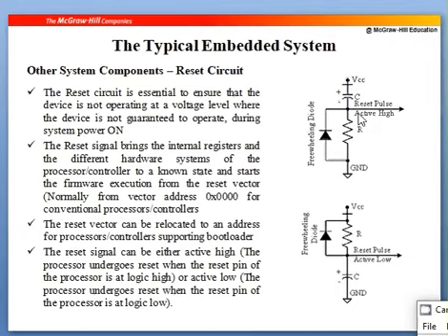Initially this will be active low, and it is pulled to active high when the VCC supply falls below a certain voltage. Similarly over here, initially the pin will be in the high position. Then when the supply goes bad, this will be triggered to the low position. So it is used for functioning your reset. This will be used if the pin accepts a high signal. This will be used if the pin accepts a low signal. If the reset pin takes active low, then you have to use this circuit. If the reset pin takes active high, then you have to use this circuit.